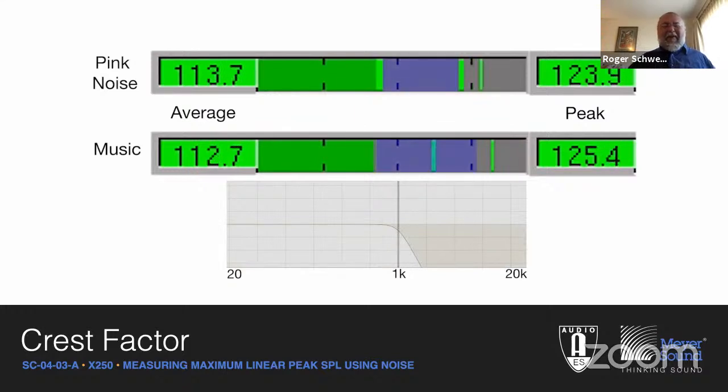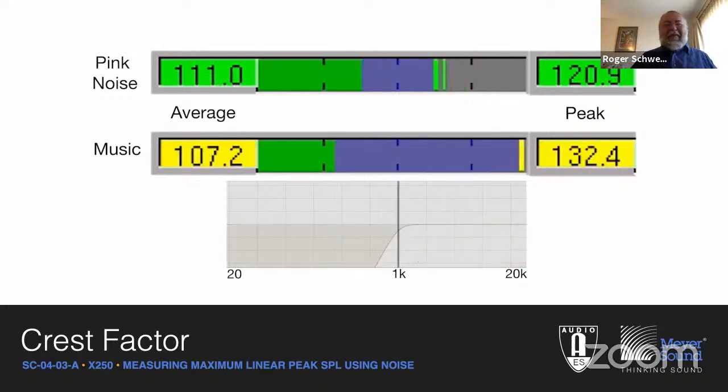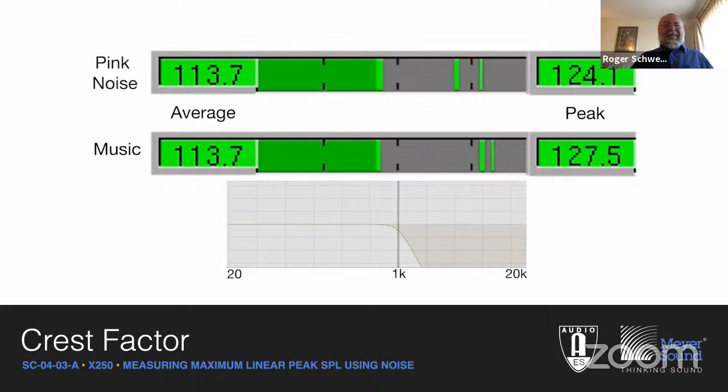One would expect, you need high frequencies to make a sharp square wave, or to make a really fast peak. So wouldn't the high frequencies have a higher crest factor? And they do a little bit when you analyze pink noise in bands. It's maybe down a dB from 12 dB crest factor at the low frequencies, and it's up about a dB in the high frequencies, but that's really the same as saying it's flat plus or minus a dB.